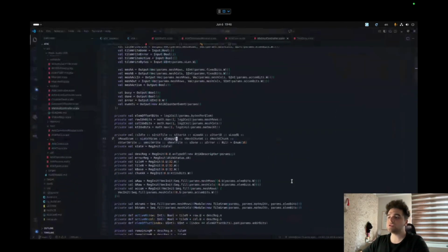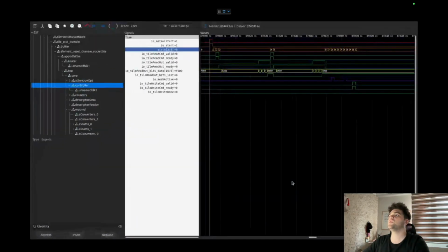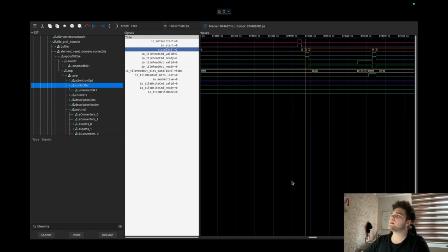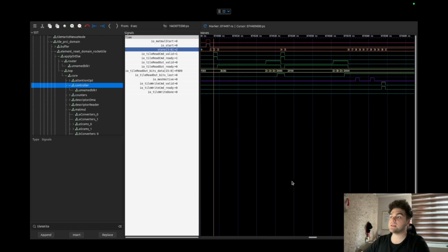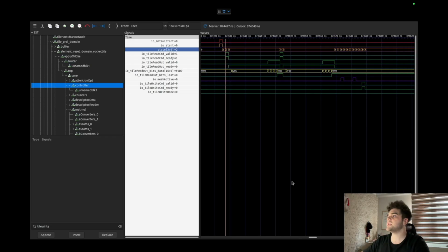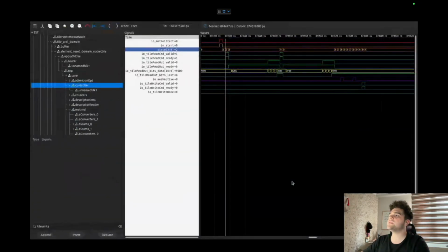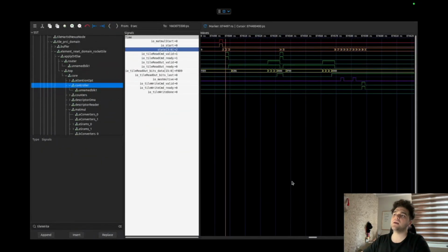As you can see here, we have a very long state machine for just the matmul operations. You can see here, it starts from 0 and it ends up at 12. So we can just follow it and trace it. I can see here that we are now at the third state. What is the third state? It is start A, and after start A, I can see that the tile read command